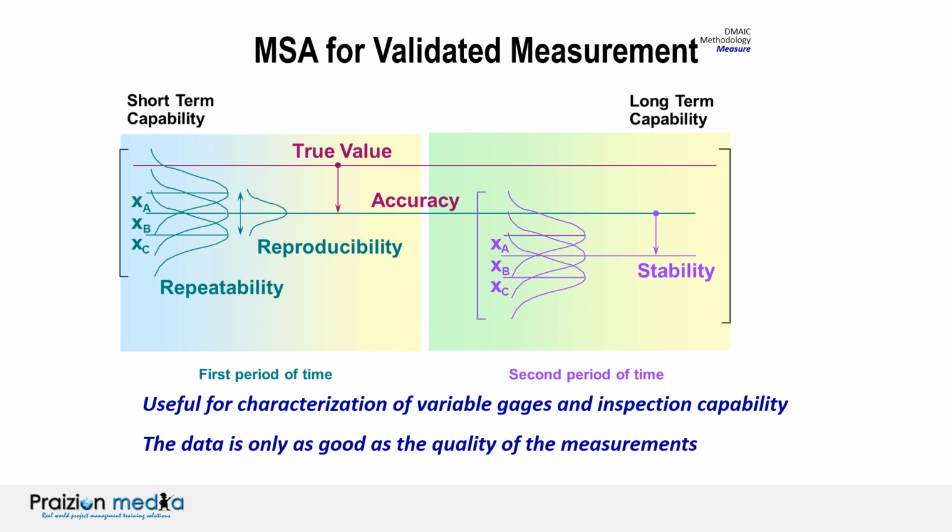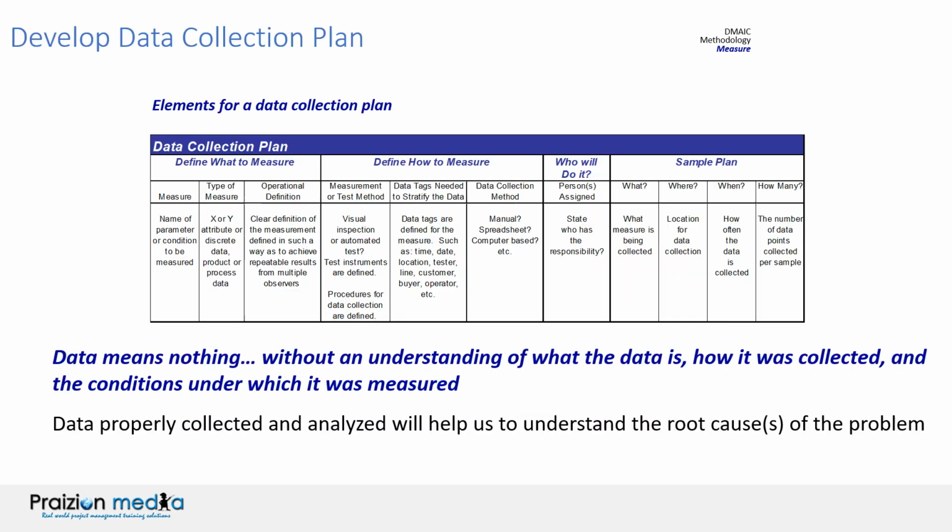If you have calibrated your system at a monthly scale and it starts differing every 15 days, that is probably either your calibration cycle is too long, which you should mend, or your measurement gauge is drifting. For that reason, you have controls in place that you inspect at every predetermined frequency. Control is something which will be the last module, and we'll be talking about that there.